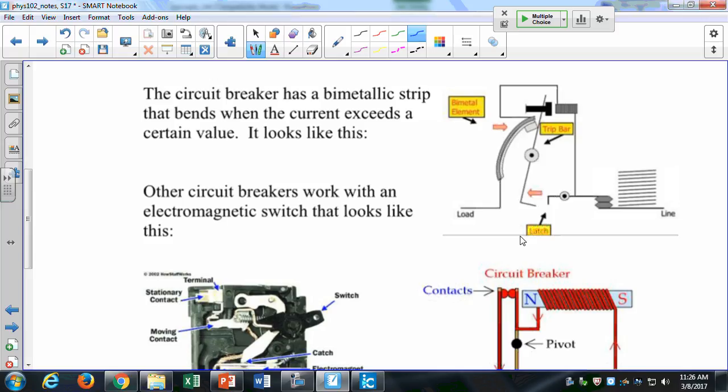So when you have this bimetallic strip, I heat one side or the other, and it can make the strip bend one way or the other, depending upon which metal expands the most. So like if this side expands more than this side when I heat it up, it's going to bend in this direction, because this side will get longer, or vice versa if you go in this direction. And so that's what this does, is this bimetallic strip will bend one direction or the other.